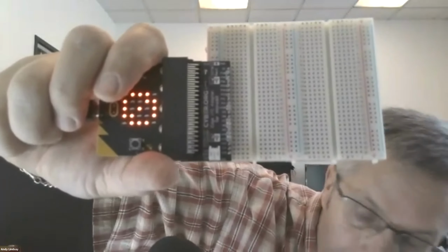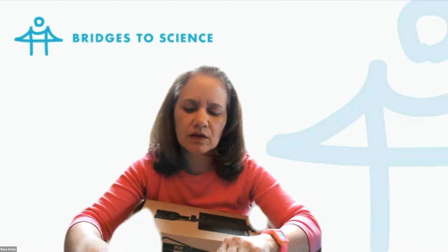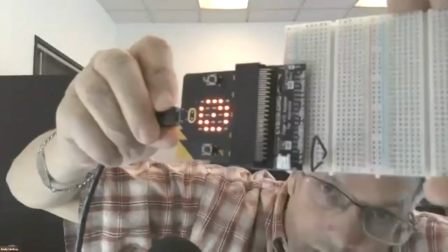Well, actually, let's really make sure nothing is defective. I pulled out the 3-pin headers. Yes, I'm back to an empty board. Now what I'm going to do is take a wire and connect row 28 to row 30, in that same row of 5 with P0 and P2.